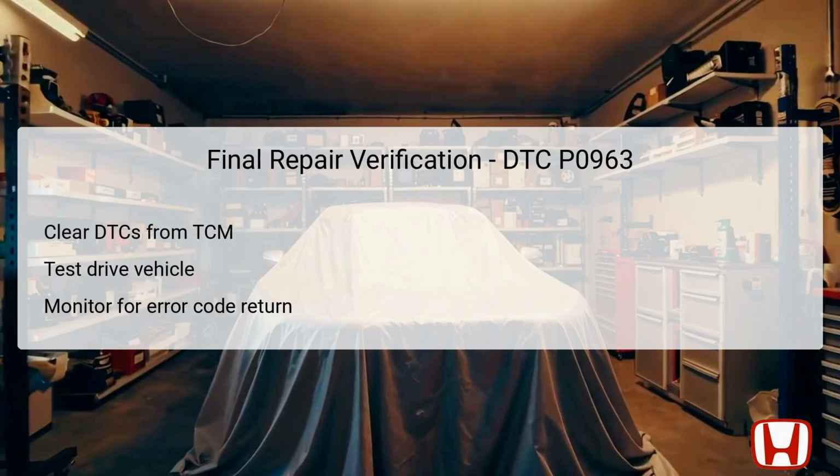After performing any necessary repairs, the final step involves clearing the DTCs from the TCM to reset the system. This is crucial as it allows the vehicle to rerun its diagnostic checks without the interference of previous codes. Following the reset, technicians should conduct a test drive of the vehicle under various conditions to ensure all systems operate